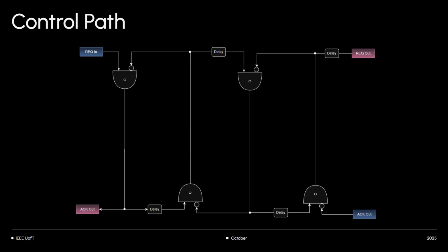The purpose of this acknowledge out is for the receiver to tell the pipeline, and through that the sender, that I have received the data, you don't worry about it. And this is where it differs from the conventional synchronous pipelines. The acknowledge out that we sent, remember, we toggled this acknowledge line. Did that wave get through the whole thing? No, right? The request got through, but the acknowledge just got through this stage, just this stage. That's it. It only cleared off this stage.